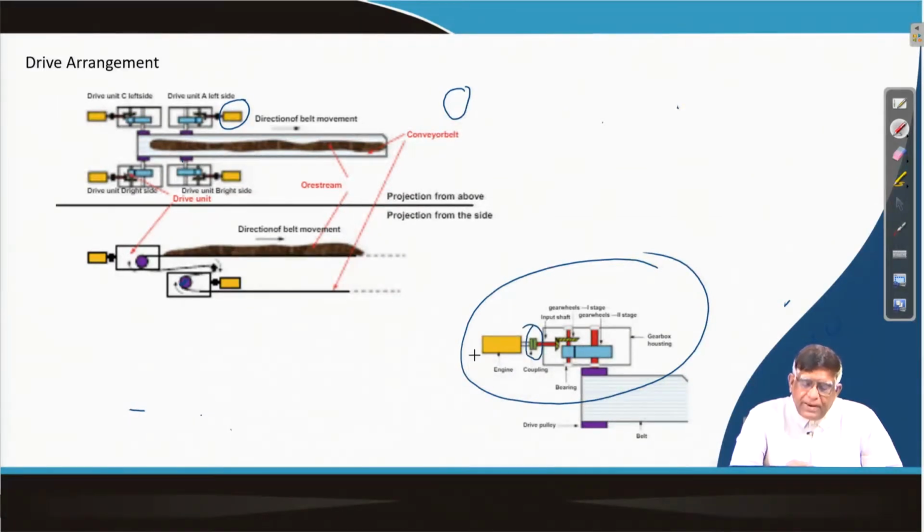What type of coupling you select is very important, and what type of gearbox you use is important. The gearbox shaft will be mounted on some bearing, so what type of bearing is selected matters. Then how it is connected to this shaft, whether you use a spline, and the other coupling you have there, are also deciding factors. So while designing the whole thing, we go into the intricacies of each and every point.